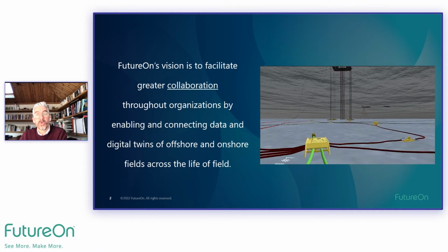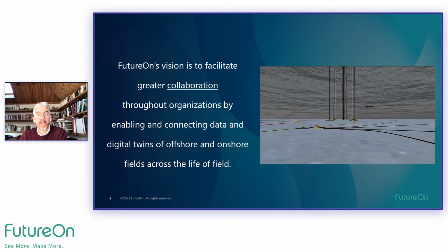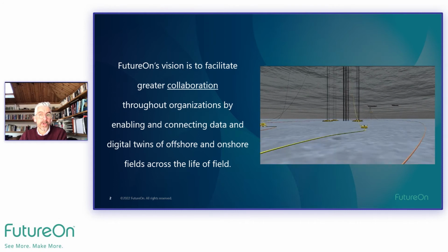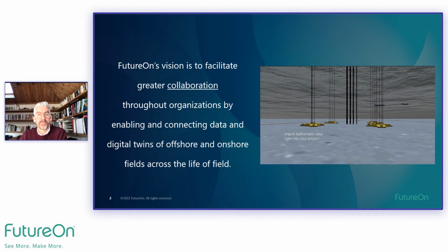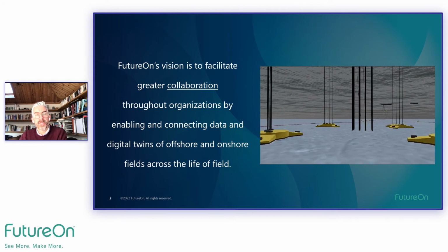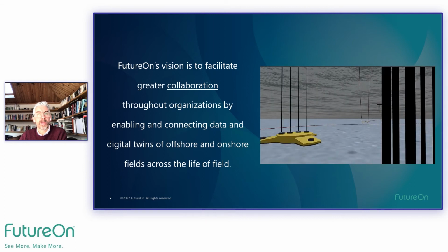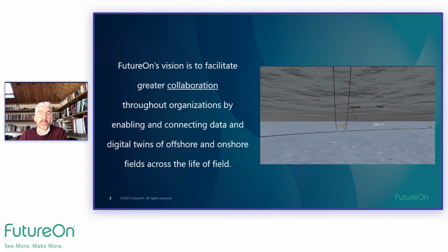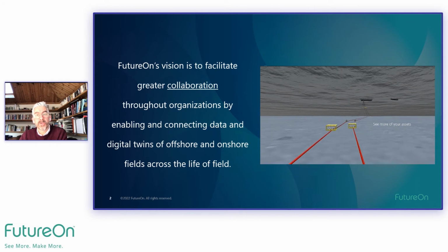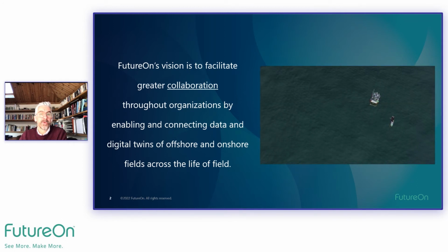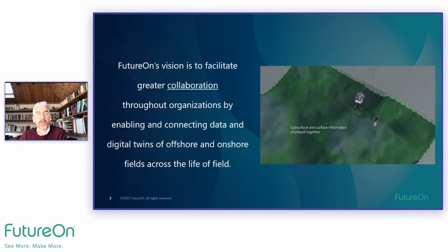The platform provides both generic and contractor asset libraries and catalogs with 3D models, which can be dragged and dropped onto the screen, similar to Visio, creating a subsea field, and then connected together using pipeline models, risers, umbilicals, and flying leads. So each asset and connection can then have an associated set of metadata, which describes the functional and physical properties of the equipment.